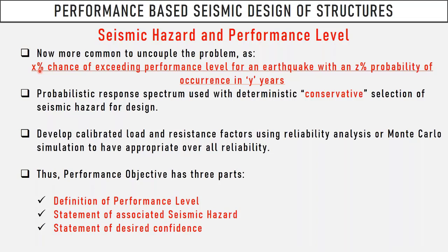Of course, while we are using this approach, we use a probabilistic response spectrum, which is less conservative than the seismic in that region. We know that. That's why what we do, we develop a kind of calibrated load and resistance factors that I mentioned, again using reliability analysis, or in very rare cases, Monte Carlo simulation, we can come up with an appropriate overall reliability.